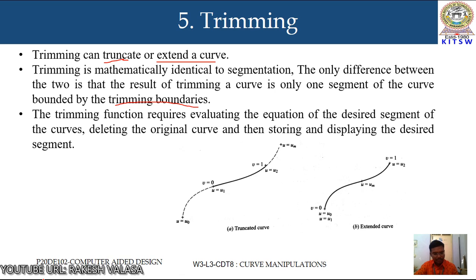Extending general curves such as cubic splines, Bezier curves and B-spline curves may not be recommended because the curve behavior outside its original interval, u equal to u0 less than u less than um, may not be predictable.